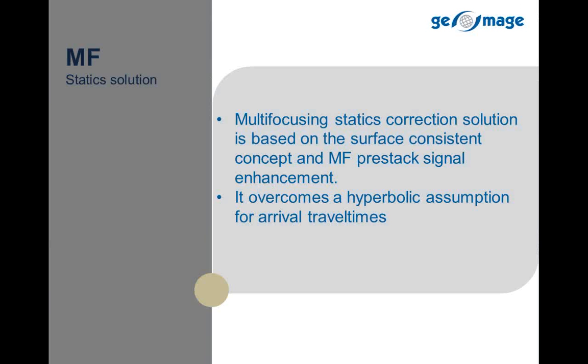The multifocusing static correction solution is based on the surface-consistent concept, which is used in conventional processing, but we use the multifocusing pre-stack signal-enhanced gathers to estimate the time shifts and the necessary pilot traces in the static solution.